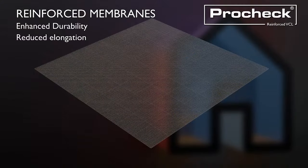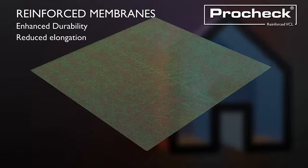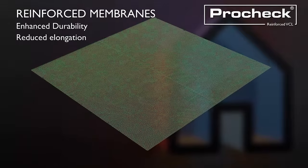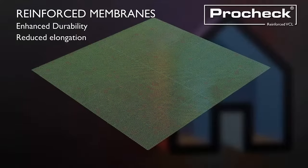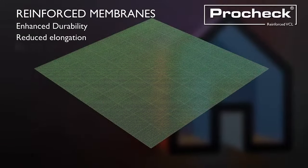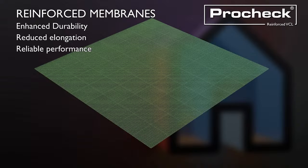Two layers of polyethylene with reinforcement offer a significantly more durable material, less prone to stretching and elongation, while it's much harder for accidental damage to spread due to the tough reinforcement mesh. This helps to ensure the performance achieved at the design stage is matched by the final as-built result.